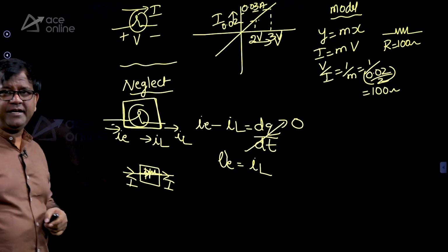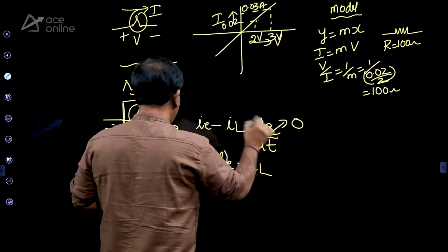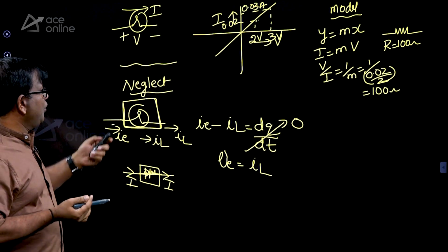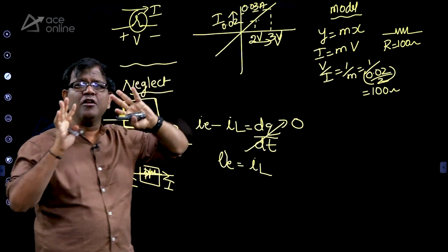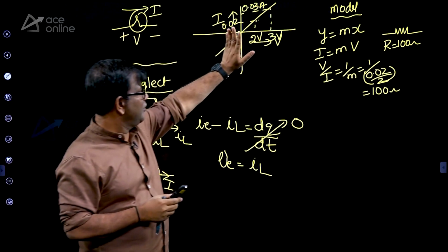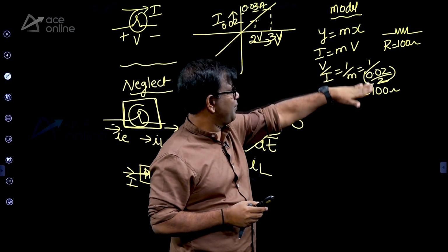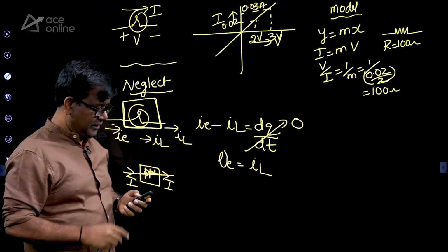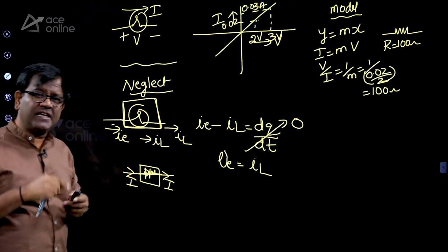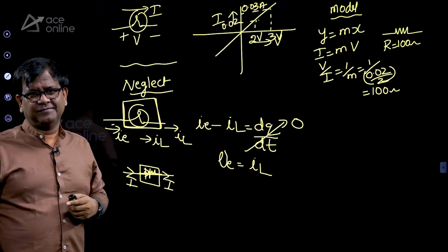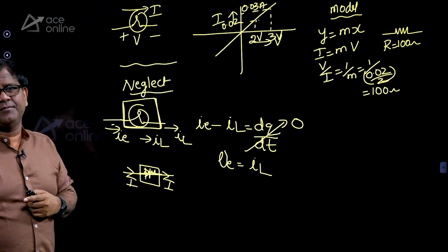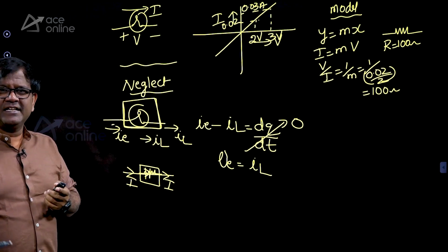You can put a resistor here, you can put a bulb, you can put a diode, whatever you want, right? So don't talk about the interaction inside, don't talk about the interaction outside, worry only about current and voltage in an analog problem. Define voltage and current for a device, from the characteristics prepare a model and solve. Suppose the examiner gives 3 devices. For every device, thinking about the interaction inside is a waste of time.